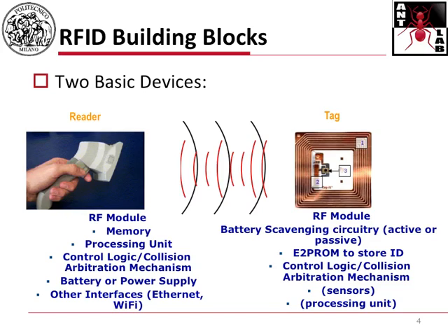The problem of this process is that you have multiple tags which might answer at the same time, which means that you might have collisions at the reader. So to avoid this collision, as we will see, there are several arbitration mechanisms, which are basically mechanisms to handle concurrent multiple transmissions from the tags to the reader, such that the reader is able to identify all of them.